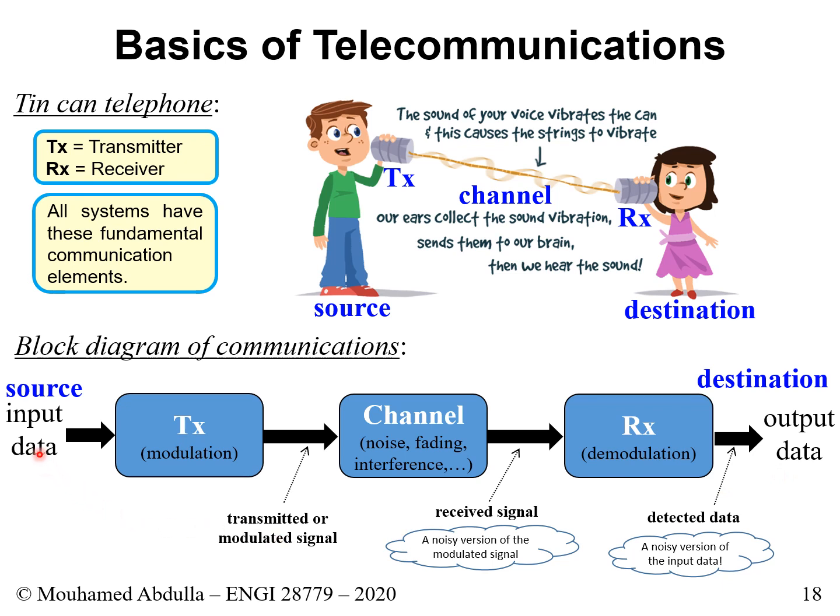If you are sending an analog signal, some signal that varies over time with various values of voltages or current, then what you get here will be perhaps an attenuated version of it. Certainly it will be attenuated, and it will also be corrupted, and it's corrupted because of noise. We'll see examples of that when we look at AM and FM signals later on in the course. Okay,